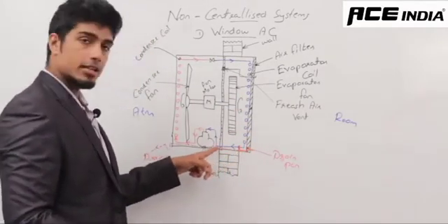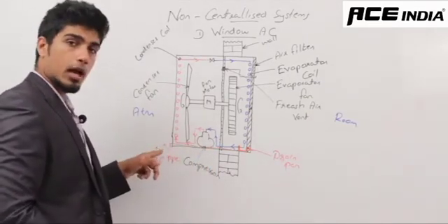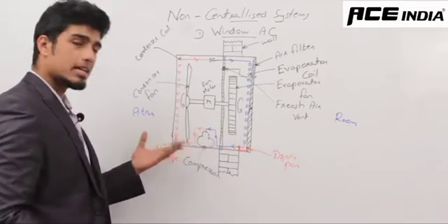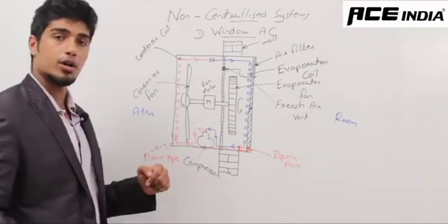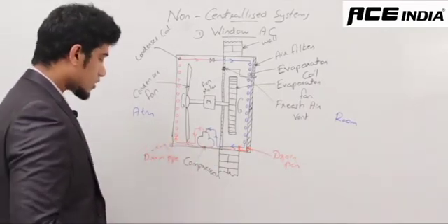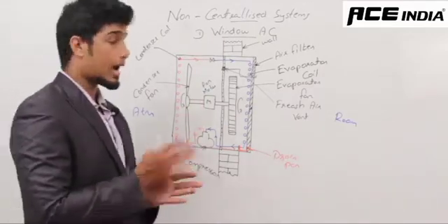It goes through a PVC pipe like here, which is called a drain pipe. It comes out with the U-trap. The U-trap is provided so that the smell won't come here, and also some insects or something like that will not actually go into your indoor machine. So it will come here, go through your drain pipe and U-trap, and go out into the nearest drain point.